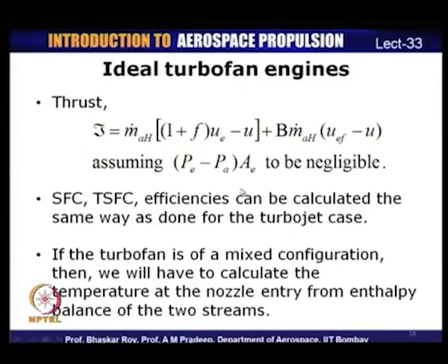Of course, there will also be a pressure thrust term. If it is assumed negligible, then this is the total thrust developed by this turbofan engine, the ideal turbofan, where the two streams are unmixed. Now, similarly, we can calculate the thrust specific fuel consumption and the efficiencies in the same way as we did for the turbojet case. And once we calculate thrust, the other parameters are straightforward.